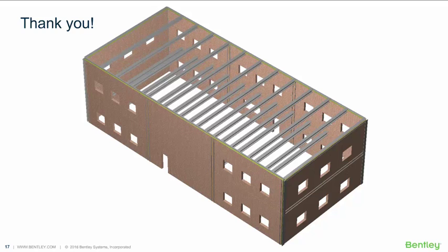So it places more soft nodes, being the analytical nodes that it places in between physical objects, in the areas where there's high concentrations of hard nodes. In other words, hard nodes being, for instance, the corner of an opening or the end of a wall. And that's nice because it allows the mesh to still be pretty coarse in areas that are wide open, where there's not a whole lot of need for refinement. So I'll start with about 4 feet. A long answer to the question, but I start with about 4 feet and handle it that way. And if that doesn't resolve it, then I'll consider decreasing the mesh size a little bit further.